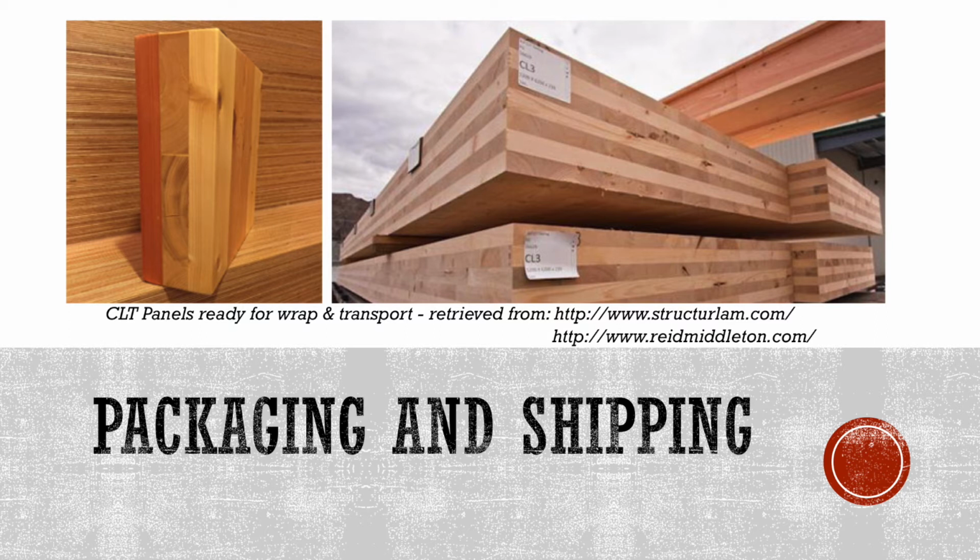Prior to getting shipped to the site, the CLT panels have to pass a final inspection by the manufacturer's quality control personnel to ensure that they meet the client's requirements. The panels are often enclosed in shrink wrap to protect them from the weather and external damage during transport, storage, and placement at the job site.